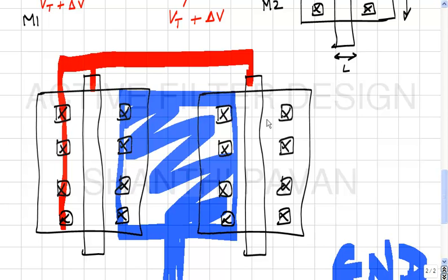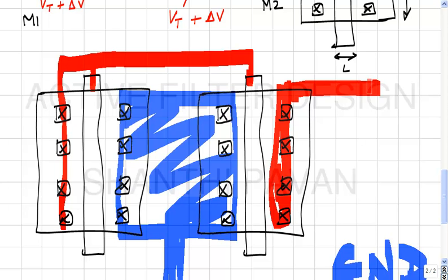So to tap the output current, what I probably would do would be take this wire, and now this wire, if its potential is higher than a certain minimum, will appear like a current sink. Okay. Now the input current pumps into this node. All right. So can somebody comment on, and please note that this current will be exactly the same as I. Okay. Under what all assumptions?